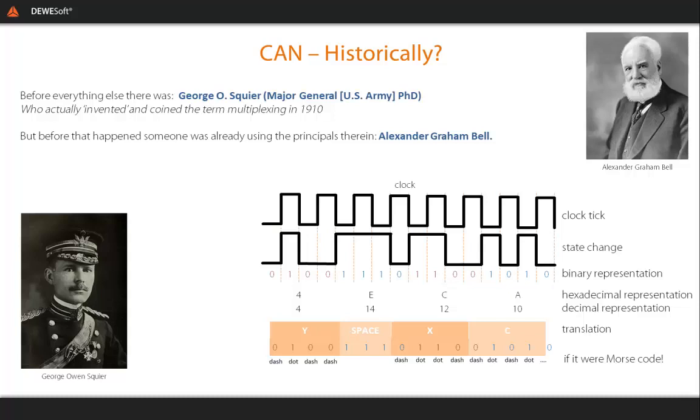The signals illustrated represent what early multiplexing and clock-based state changes may have amounted to. The example illustrated introduces a number of useful aspects of communication protocols: the state, binary, hexadecimal and time period relationships, and we'll cover these later. If it were simply binary, it could be 010011 and so on, seen below the signal.